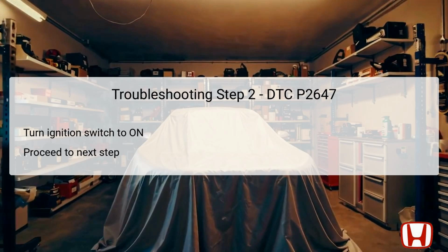This procedure is standard practice for initiating any electronic component examination and should always precede accessing diagnostic functions. After turning the ignition to on, technicians should then proceed to the next troubleshooting step to continue assessing the VTEC system functionality. In this troubleshooting step, the technician is tasked with clearing the diagnostic trouble code, DTC, using the Honda